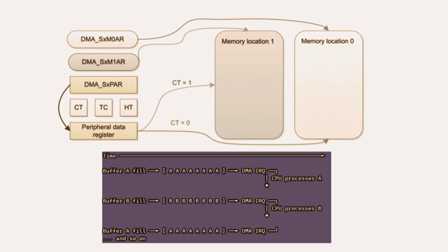You provide pointers to both buffer A and buffer B. Then you need to implement the DMA transfer complete callback, the ADC conversion complete callback, and potentially the half-complete one too. But now your logic inside the callback needs to know which buffer just finished filling so it can process the correct one. The HAL library often helps manage this state. So the callback knows if it needs to process A or B? Yes, essentially. You process the completed buffer while DMA works on the other one.